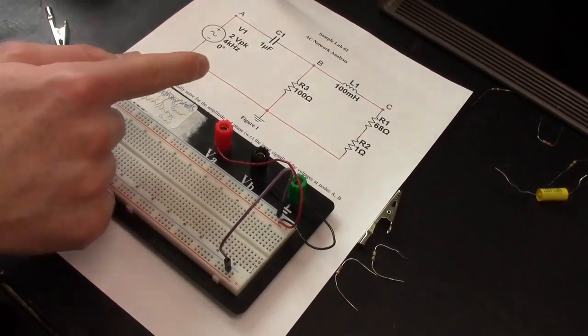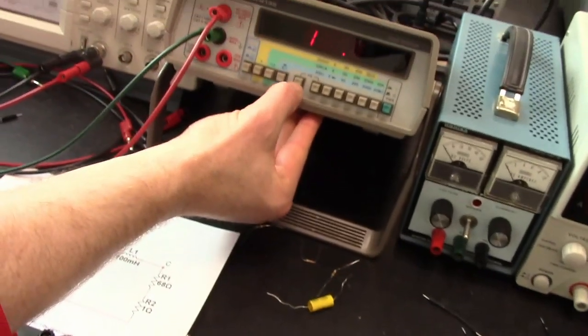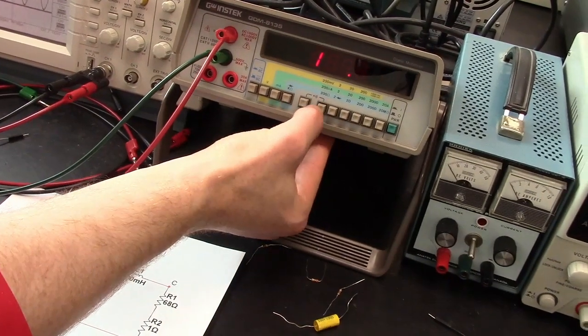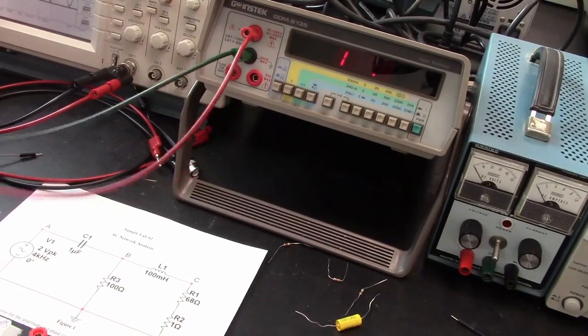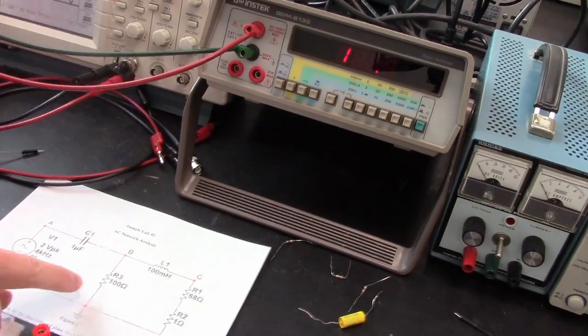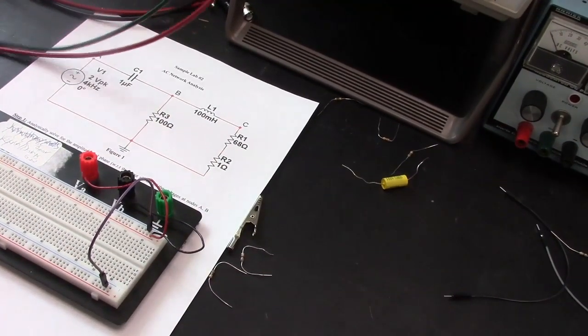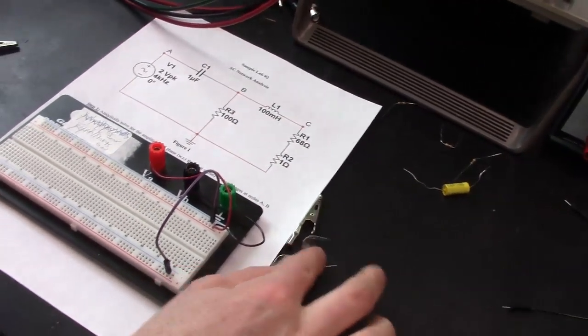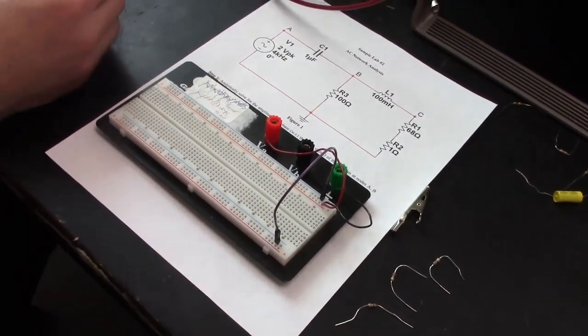Next part, we need to get the resistors measured. So up on our multimeter, we'll turn off the sound to make that a little bit less obnoxious while we're measuring things. And now we're on the 200 ohm range, which is going to be the perfect range to measure the 3 resistors that we have, 100, 68, and 1. So I've already gotten these resistors out of the drawers there.